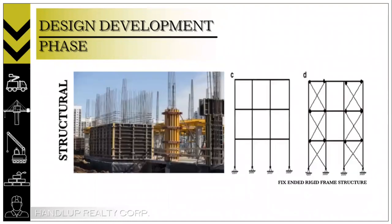Then, the structural engineer would decide what kind of structural framing the building would need. For our case, the engineer has decided to have a fixed-ended rigid frame structure for its structural framing. The structure of a steel rigid frame building is characterized by its rigid connection of straight or tapered columns and beams. These structures look similar to that of a post and beam system.